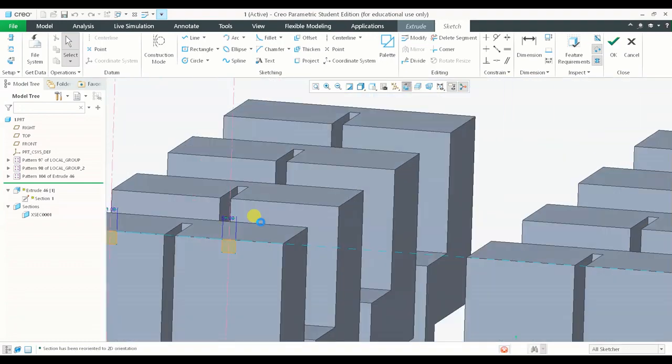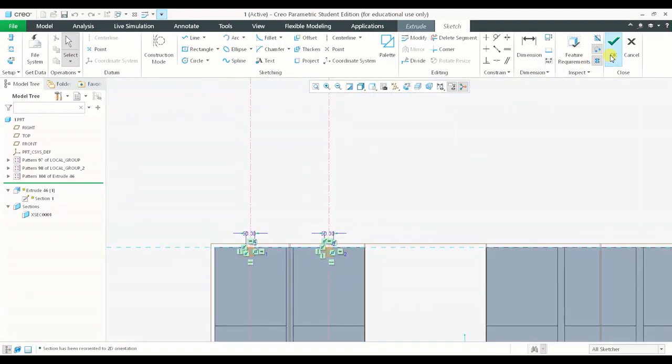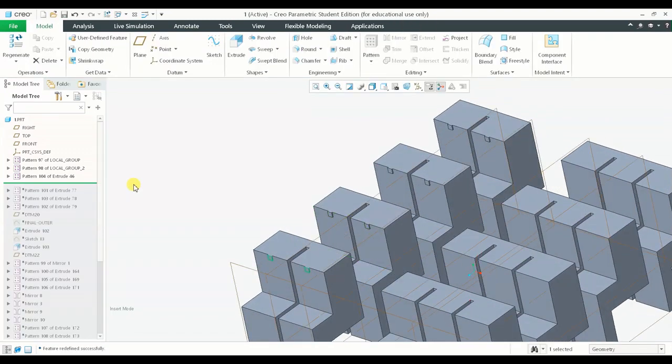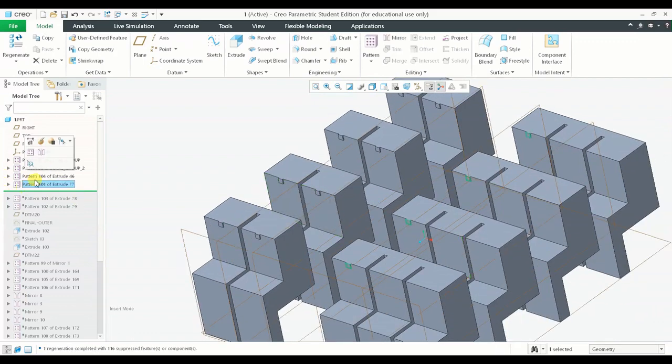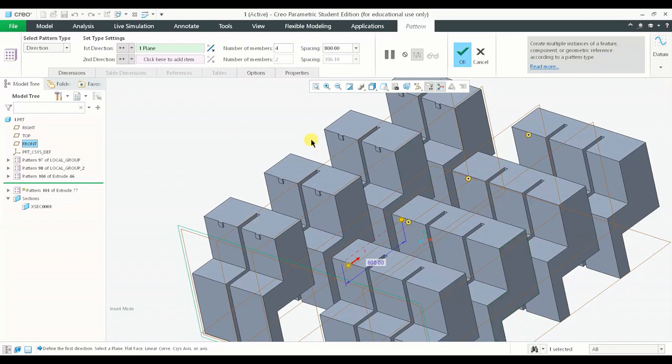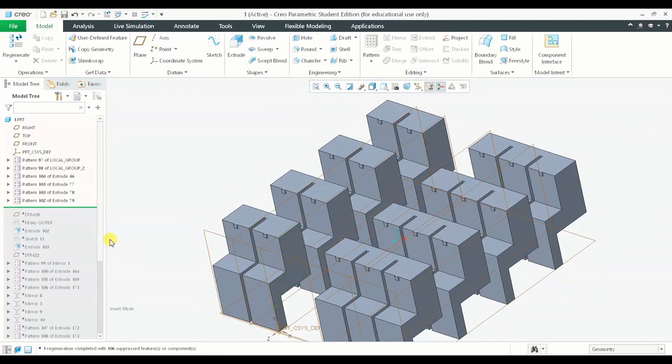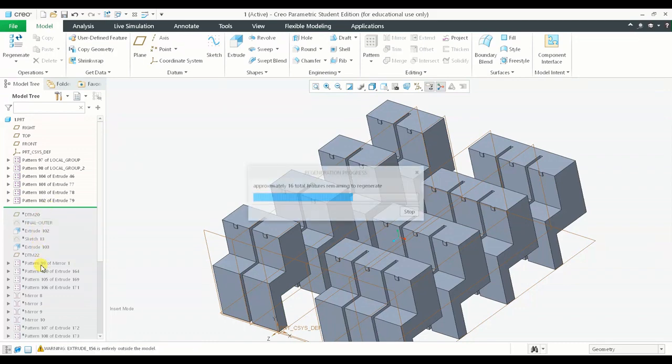You can see the sketch over here. Clear? And this was extruded for a certain distance and it was patterned. Then again this was patterned on the right hand side using the direction pattern. And just remember one thing, for all the patterns which you're finding in this model, I've utilized only the direction pattern because that was enough for me, and it was not required for me to use any dimension pattern or any other pattern which are present. So in this way we have created the different features in a step-by-step procedure, and we have created the total geometry.